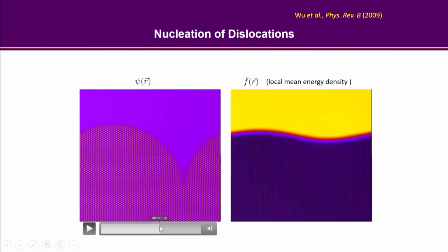one dislocation is occurring at some place. As we showed a few days ago, if you see one edge dislocation, you are expecting one lattice plane missing above that edge dislocation compared to below it. So by forming that dislocation, there will be one extra lattice plane below, because you probably already have 30, 40 lattice planes and you compress the system.